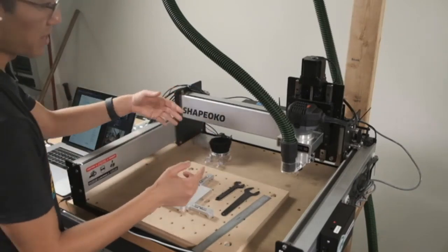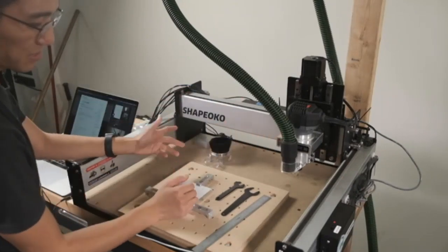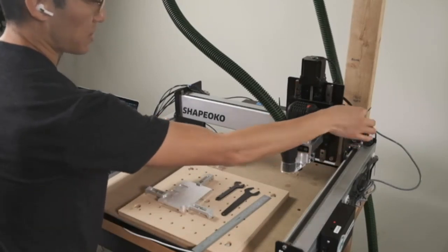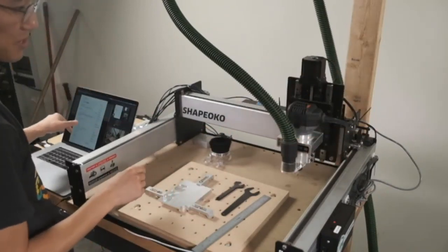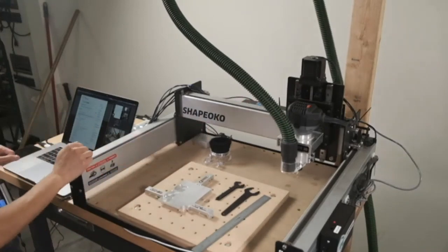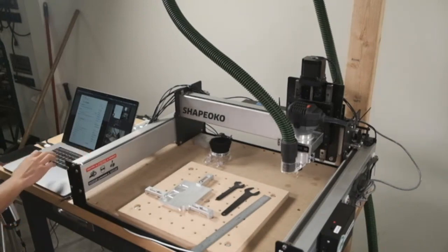If there's EMI going into a stepper motor or a limit switch, that's not as big a deal. So if it's an issue for you, try routing the router cable in the opposite direction away from your USB cable. Other than that, it can be in contact with whatever. Doesn't matter too much.